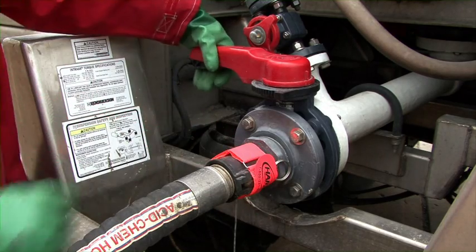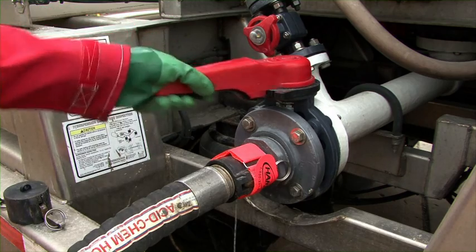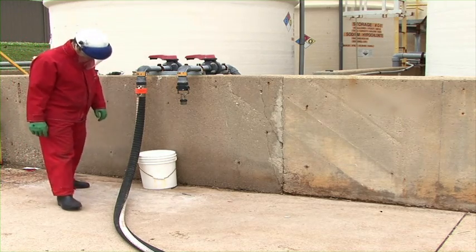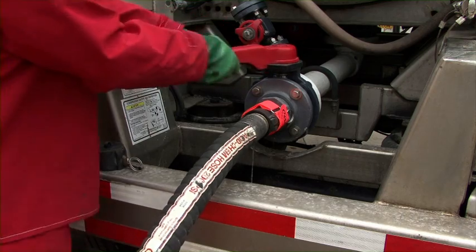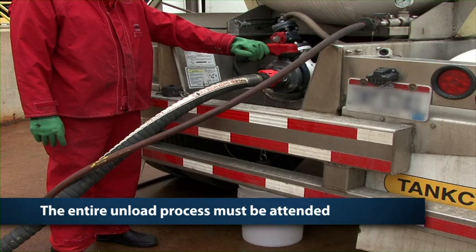Inspect all valves for proper position, then slowly open the unloading valve on the shipping container. Once the transfer has started, inspect all transfer lines and connections for leaks. If a leak is detected, stop the transfer and correct the problem. DOT and Transport Canada regulations require that the entire unloading process be attended.